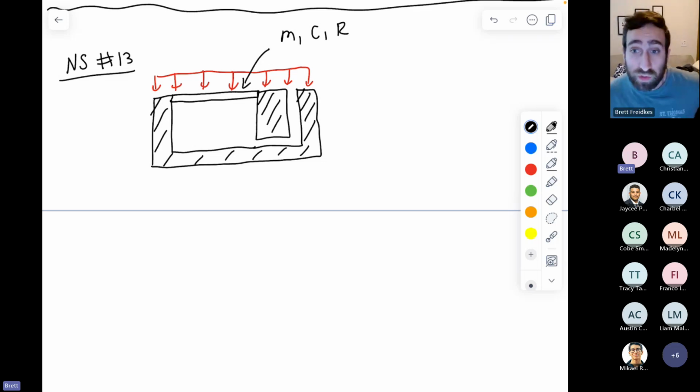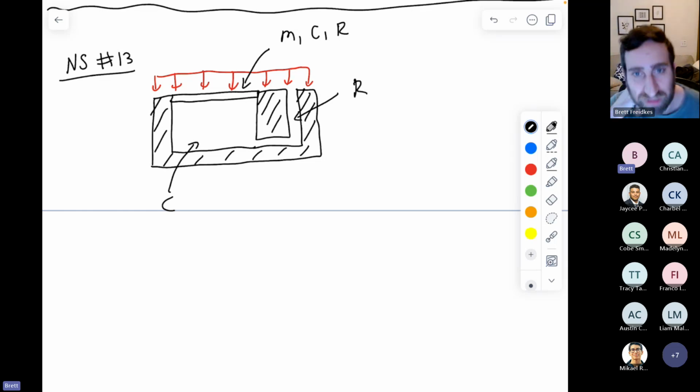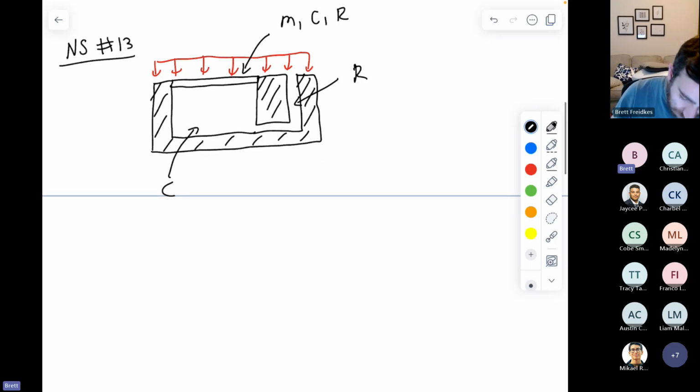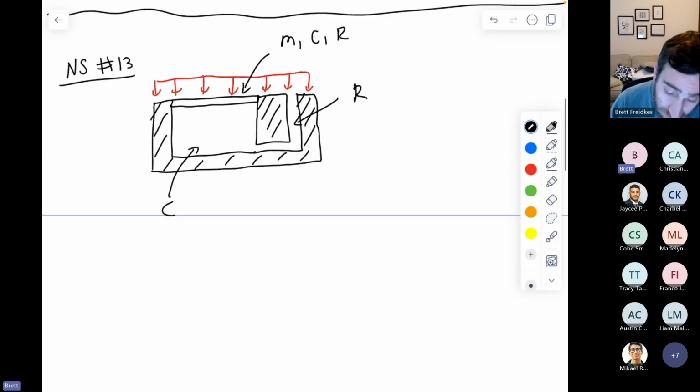The cavity we discussed had what? We're going to neglect a lot of things, but the cavity had only what, if somebody wants to unmute and answer or type. That's correct. It only had a compliance. And the vent, we said, only had some resistance. If we assume that the diameter of the vent's very tiny and it won't be storing any kinetic energy, it'll just be strictly there as a dissipator. So that's how we will go ahead and represent the vent.